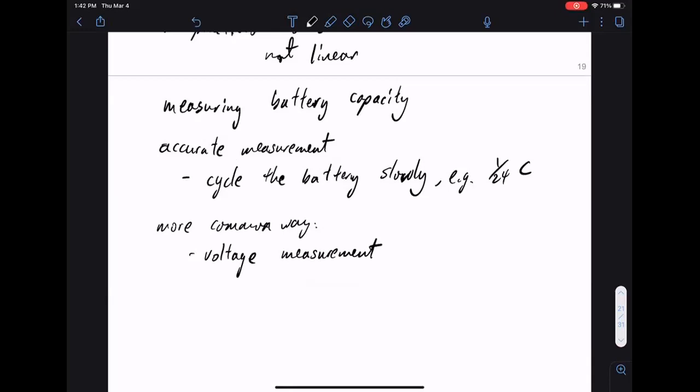Okay. So what happens as the battery degrades, the voltage when you discharge it sometimes looks like a voltage source is outputting power. And that voltage appears to be lower and lower as the capacity fades. Okay, so often you estimate by measuring that voltage in your battery. This is not very accurate. Okay, this is not terribly accurate.